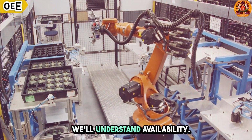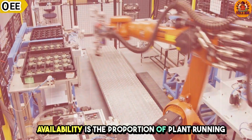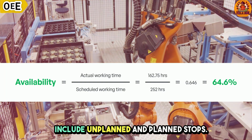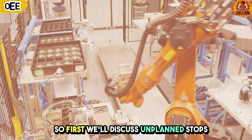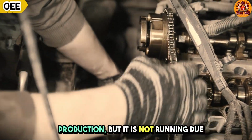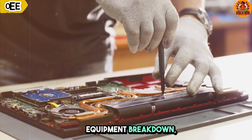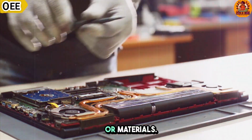First, we'll understand availability. What is availability? Availability is the proportion of plant running time that is available for production. The losses in this category include unplanned and planned stops. So first we'll discuss unplanned stops. This is the time when equipment is scheduled for production but is not running due to unplanned events like equipment breakdown, unplanned maintenance, lack of operators or materials.